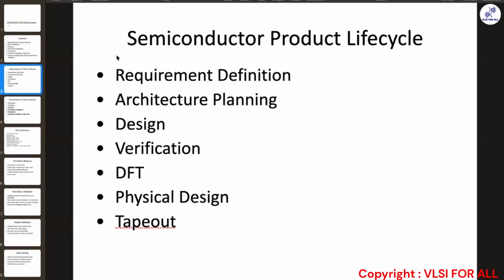With the help of DFT, you will be able to read those particular registers. You might have heard about JTAG. You may need to use that interface to access the registers inside the SoC, so that if you find any related bugs, you can debug them. So you are inserting that logic in this phase so that in the post-silicon validation timeframe, you can use it.